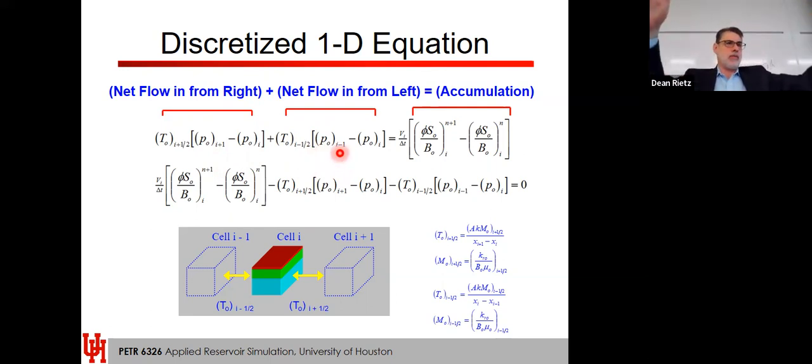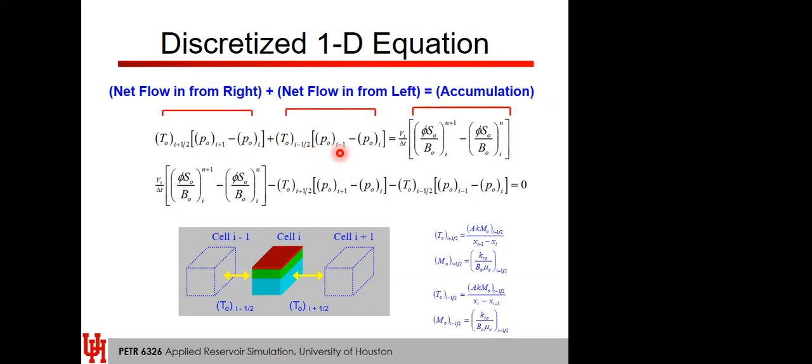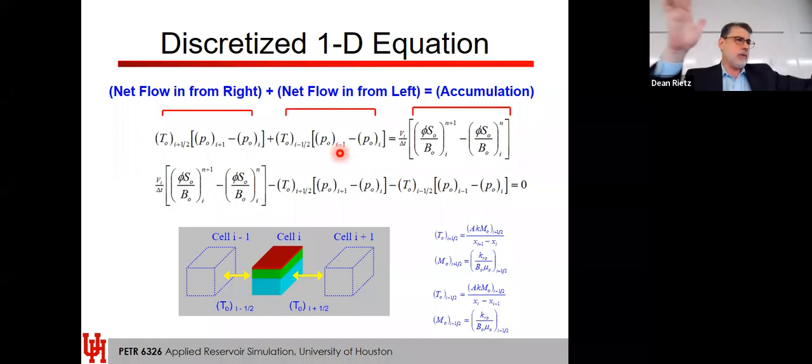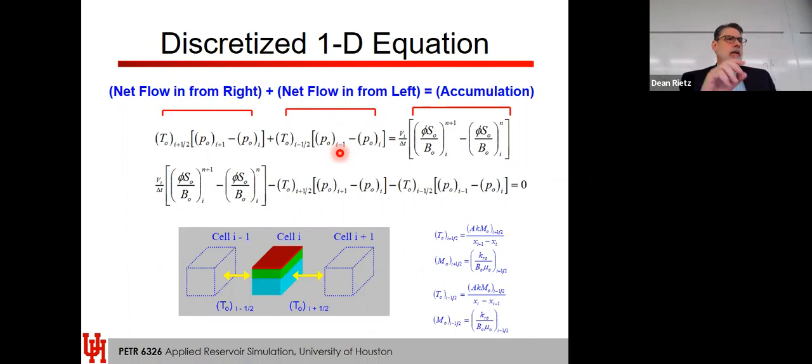So basically we have these values for this grid block, and remember, we're using Darcy's law. The assumption is everything is between the two cell centers. So we have a value of mobility for this grid block, half of it, and a value of mobility for that grid block, this half of it, because we're looking at the difference between this cell center and that cell center. So it's a weighted average between this grid block and that grid block. If this grid block was really small and that one was really big, it'd be a small weight to this grid block versus that grid block on the mobility.